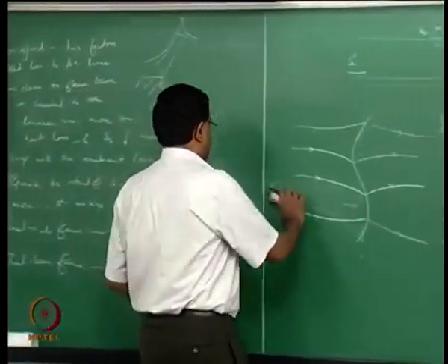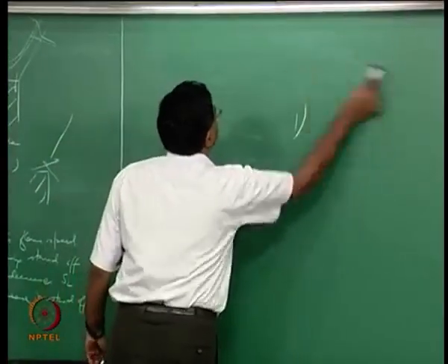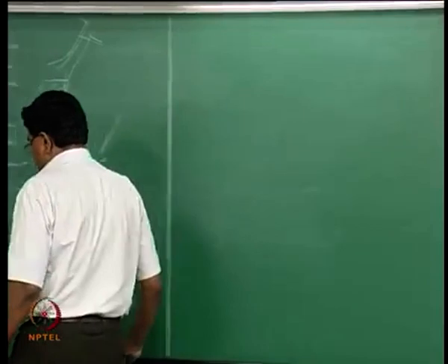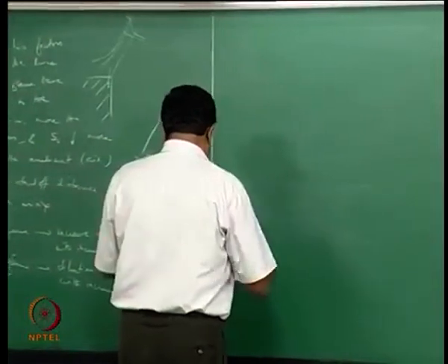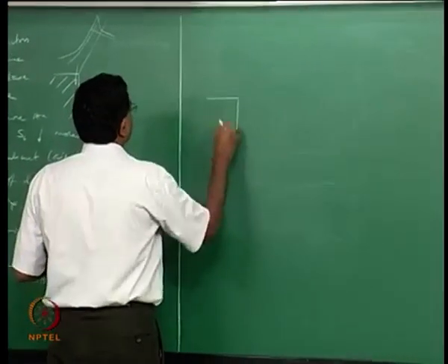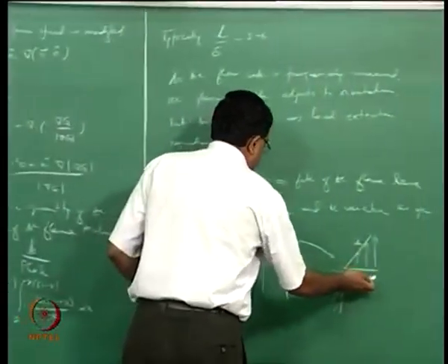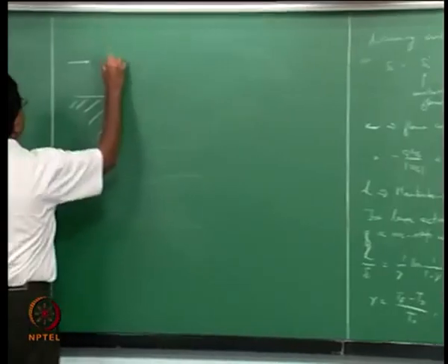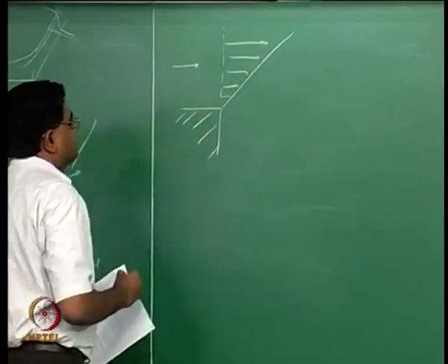With these two we should now be able to tell how the flame is stabilized. We will do this now, and we will worry about pushing the limits on this to lead to a flashback or a blow off later. So essentially what happens is, let's now put these two together. Originally, if you had a flow velocity that was locally linear, and let me now consider the flow like this, that's a flow velocity u.